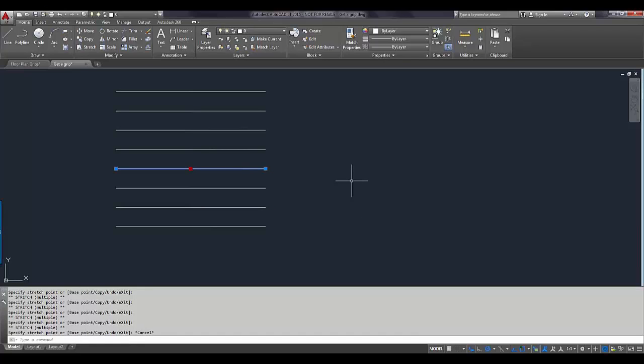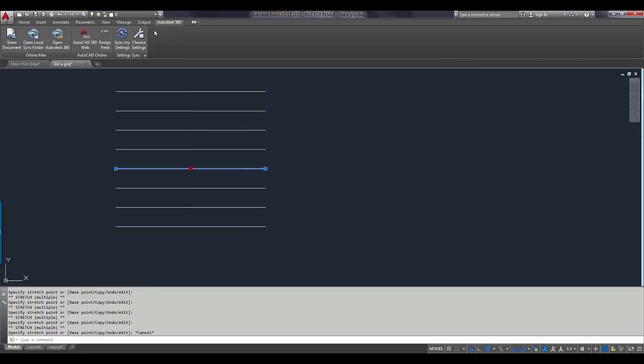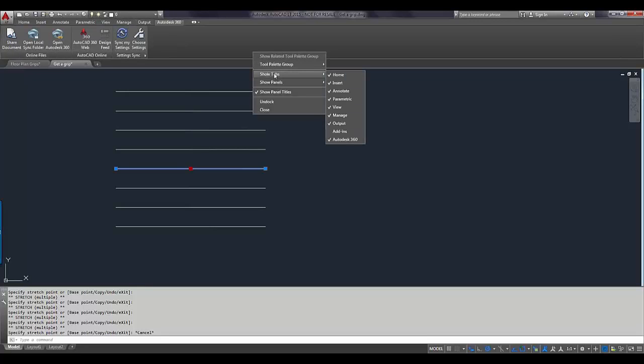And then we have another one that's a little bit off topic, but we still have some time. It was, what is the best way to turn a PDF into a DWG file? I guess it depends on what you actually need from that file. You can underlay a PDF into a DWG file and use that as a background. The other option would be something like Raster Design, which is what I used to use. That's a product that goes on top of AutoCAD, to use some line followers to help with tracing and overlapping.